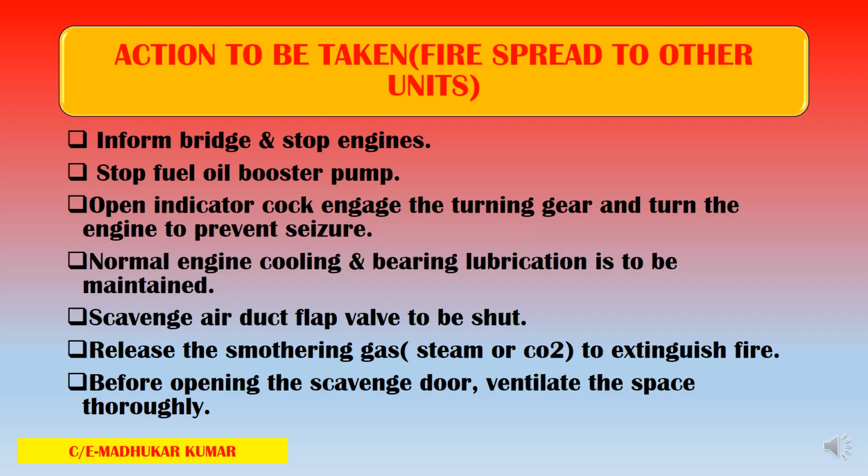Release the smothering gas, CO2, or the steam, whatever is provided as the scavenge space extinguishing medium. So whatever is there, you have to shut everything and then charge the steam or CO2. Before opening the scavenge door, ventilate the space thoroughly. When we do this, we have to make sure, especially after half an hour at least, that we wait and monitor the outside temperature, which has to reduce. If the temperature is getting reduced, then in that scenario, further investigation can be done.